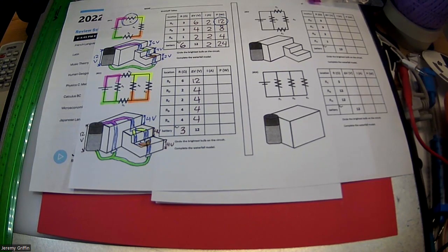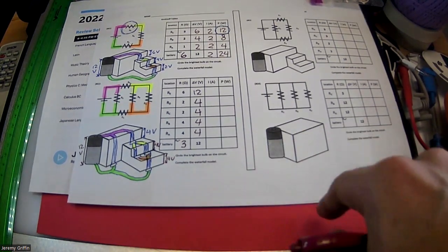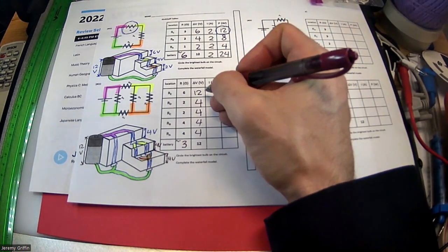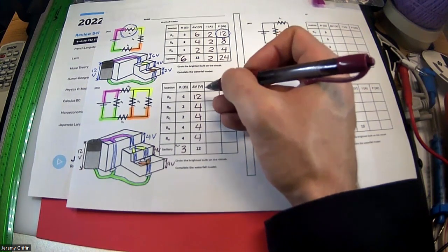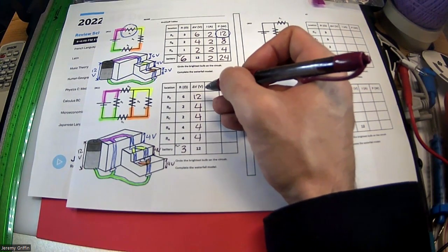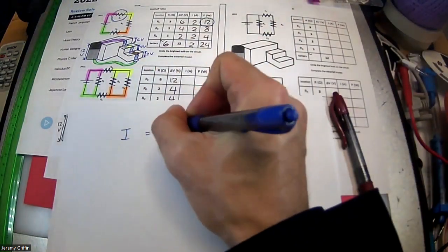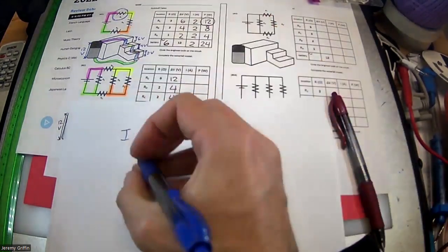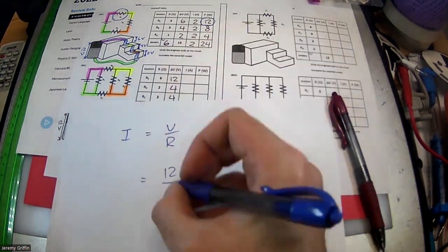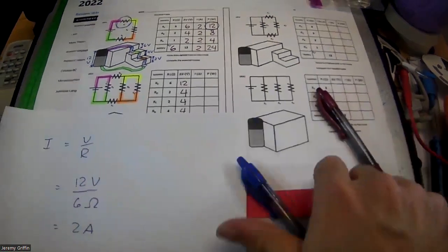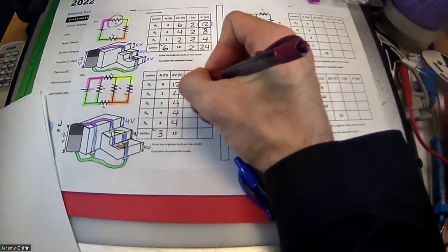That's right. Okay. So we're past the hardest part of this. Everything else from now on is a bit formulaic, but keep your eye on the principles. Make sure that everything checked out makes sense too. What's the current through each part? So the current through resistor E. We're going to go over to Ohm's law. Ohm's law: current is voltage acting on resistance. So I'm looking at 12 volts acting on 6 ohms. That's 2 amps. So current through E is 2 amps.